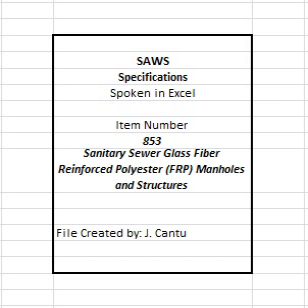to payment, 20%. 2. Materials paid on site will be in accordance with Table 1 of Specification Item Number 100, Mobilization. 3. Concrete cradles for pipes shall be measured and paid for at the contract unit price bid as provided for in Specification Item Number 858, concrete encasement, cradles, saddles and collars. 4. Gravel subgrade filler for manholes and structures shall not be measured separately for payment.